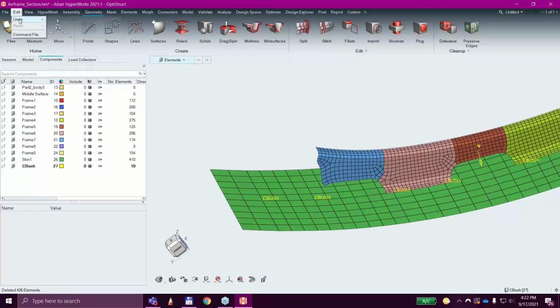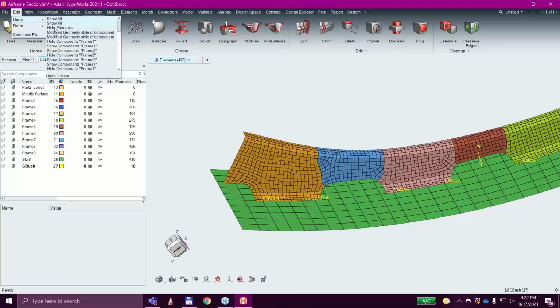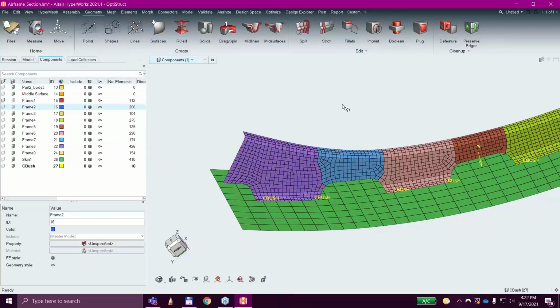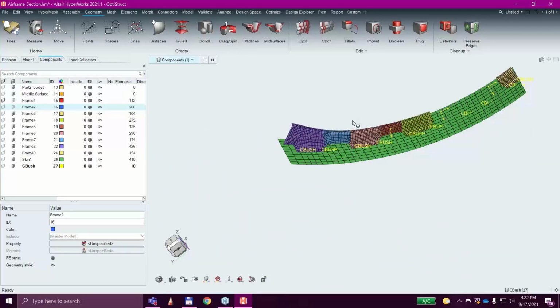We, of course, have undo functionality. So if I come up here to edit, undo, it's going to show all of the different things I had. Now, we can't just cherry pick from this undo list here. I do have to sequentially undo things. So I could undo my deleted elements and now they're back. But if I come to something a little further down, the show components, you can see everything's highlighting to that. It will undo all the way back to that functionality. So selecting something down the list will grab everything that happened since then and undo that as well.